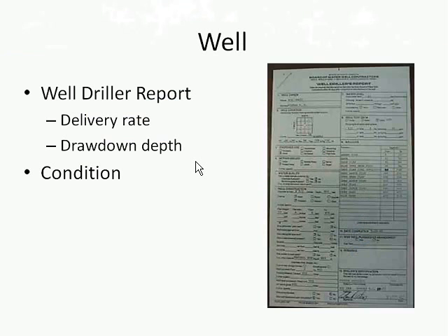Wells. If you have groundwater available, a well can be a great source of water. But there are some things that we need to consider. It's good to get a driller's report if that's available, to have an idea of what the delivery rate of water is going to be, how much drawdown depth there is, and what the condition of the water is.